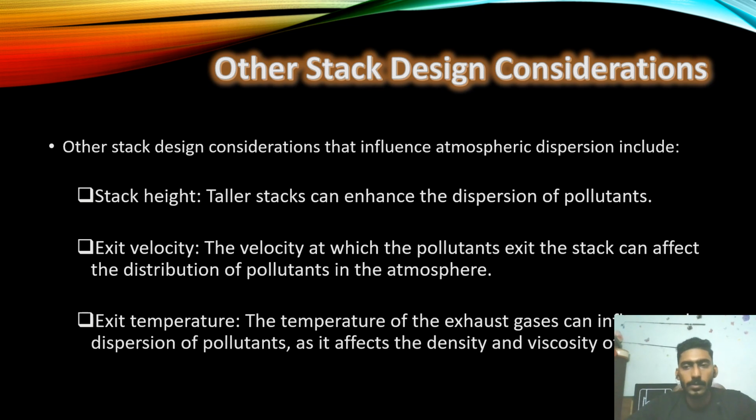Other stack design considerations that influence atmospheric dispersion include stack height, where taller stacks can enhance the dispersion of pollutants. Next is exit velocity. The velocity at which the pollutants exit the stack can affect the distribution of pollutants in the atmosphere. Third is exit temperature, where the temperature of the exhaust gas can influence dispersion of pollutants, and it affects the density and viscosity of the stack gas.